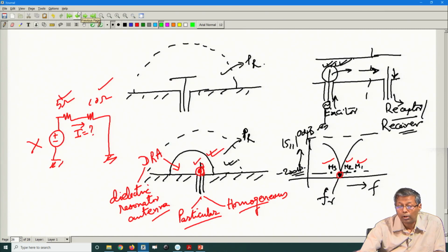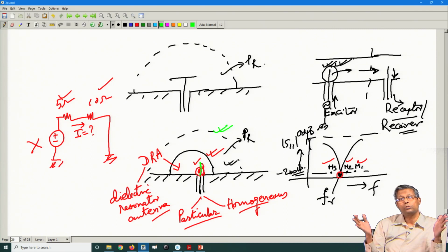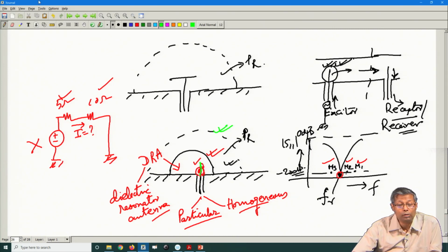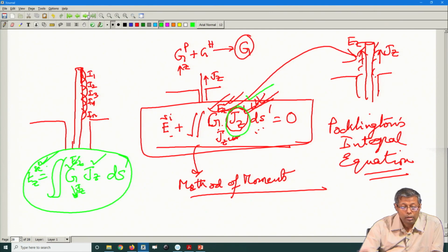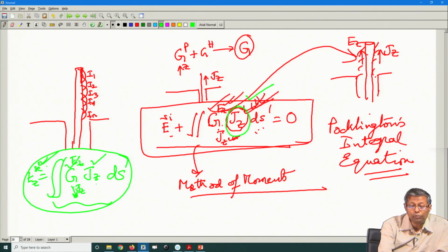As I told you before, I can find out the radiated field at this imaginary surface for one particular mode, because I already have the Green's function and I know this probe current. The Green's function is a summation over all modes. This process is called convolution. It is called convolving the Green's function with the probe current.